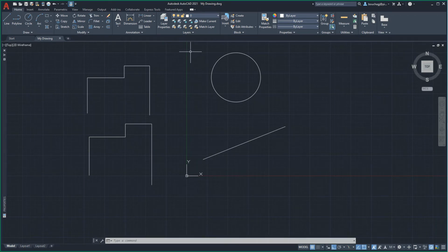When the user left-clicks at a random point in model space, the software enters the selection mode. Any movement of the cursor in the left-hand direction creates a green shaded pick box. Any object simply touched by this green back selection box is selected and recognized. One can think of the blue pick box as a more surgical method of selecting objects, especially as a drawing area may comprise many objects in close relationship in model space. Selection with a forward blue pick box is a very intentional method of selecting an object or objects.